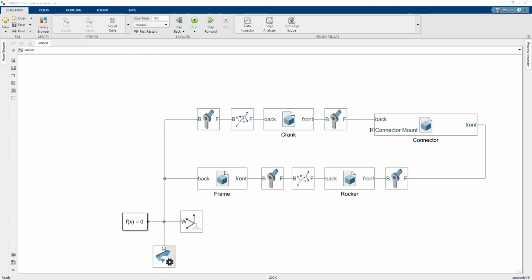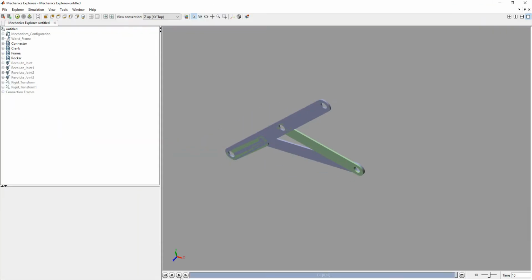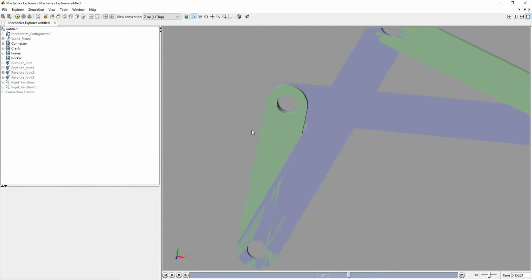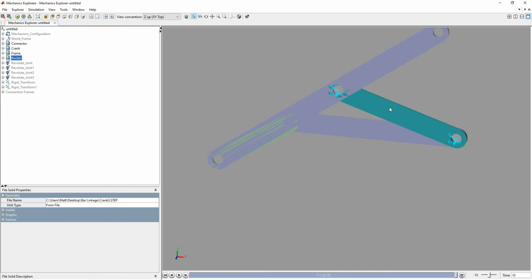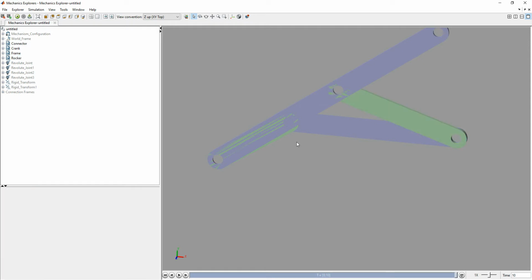Okay, so once we've done that, this is what you should get. Which is not a bad thing. Now, a few students did notice, where the hell is it getting this value from? This is just to do with the restriction between the two. You'll notice it hits some particular points and then it returns. And it's just because it's translating from rocker to crank, rocker to crank, rocker to crank. This is because it's ideal. So all this, there's no friction between the bearings, so it will just keep tilting like that.